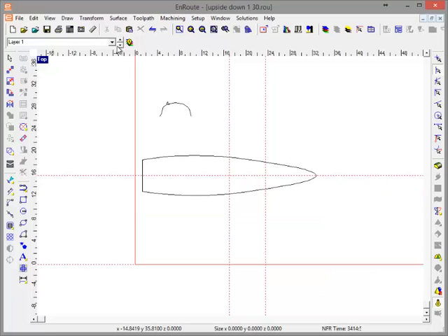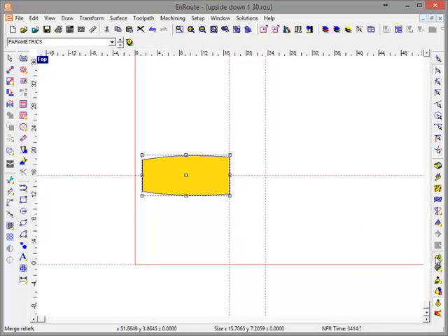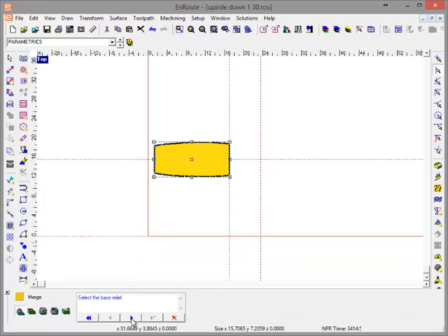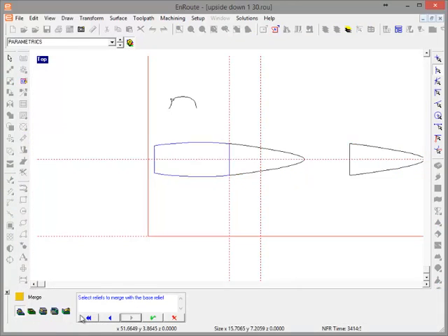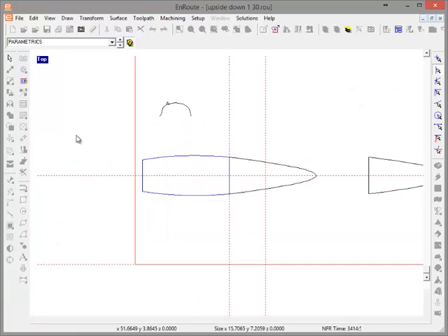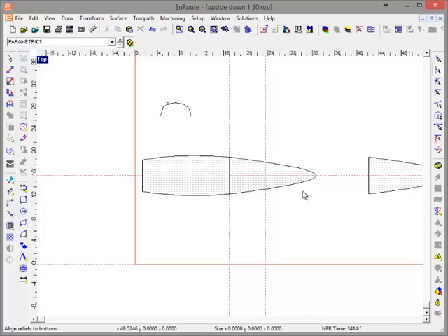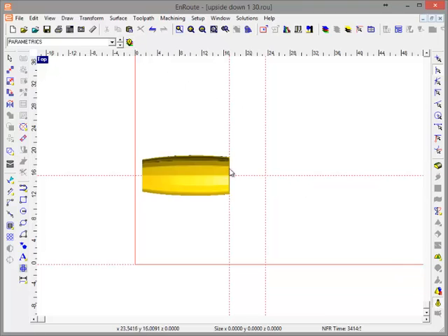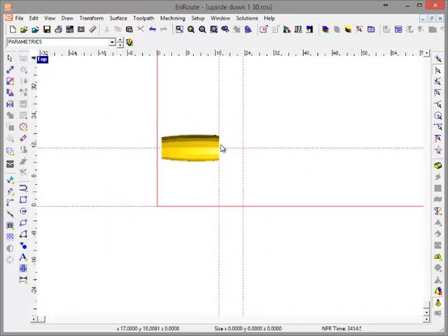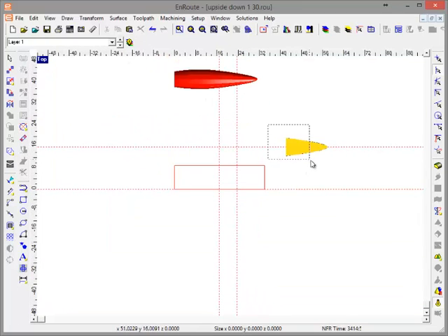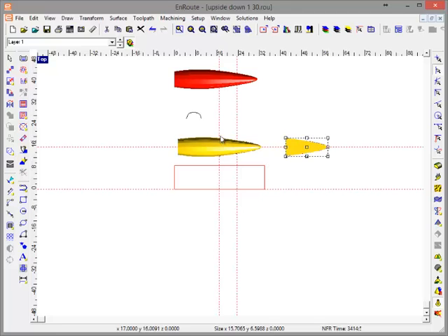Alright, so now let's come here, merge reliefs, base relief, the one I want to add, which is now here. Now I know I have the right one, and I hit add and check mark. So now I've applied that whole relief to just that one I created that was based upon a partial shape. Okay, now I kind of did this, and I need to move this part back to this other spot.